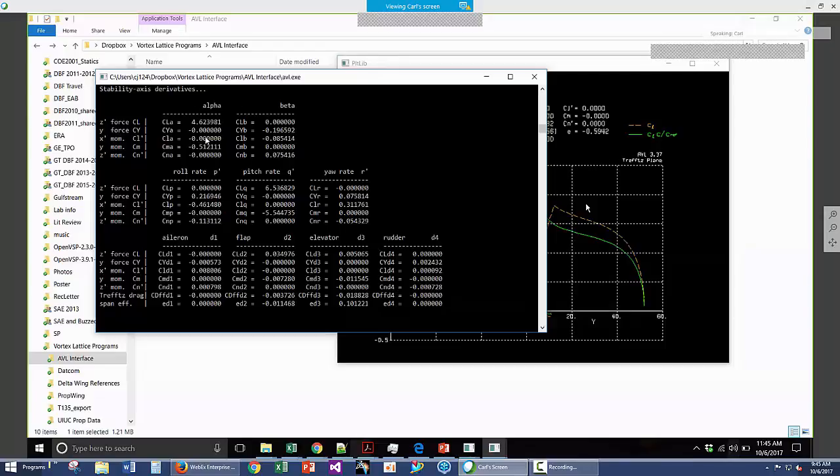Okay, that's good. We have other parameters here. CL beta is our roll stability. It has to be negative. It's a pretty strong function of CL, so you can't give a direct number of what it should be. CN beta is that weathercock stability. So CN beta here is positive 0.075.